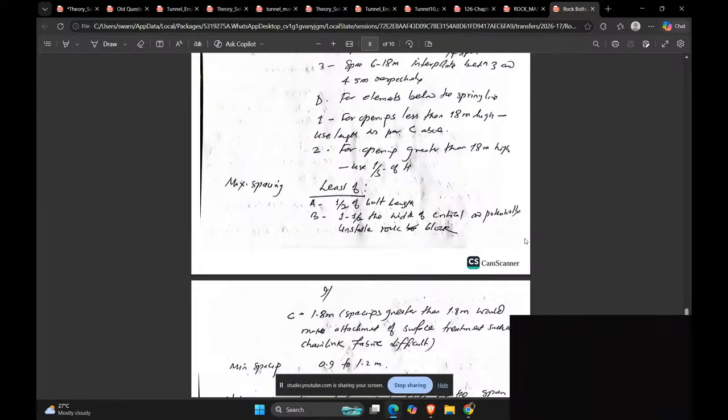And in the cross-hole seismic test, the following data was collected: source borehole depth 50 meter and receiver borehole depth 50 meter, and the horizontal distance between the source and the receiver is 60 meter. Using the travel time for the seismic wave in the cross-hole test, calculate the seismic wave velocity.